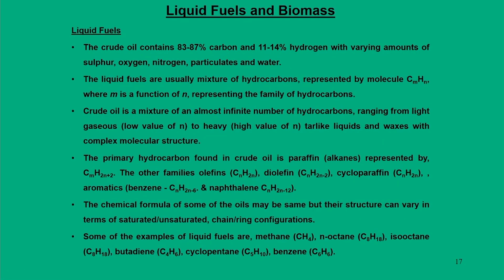So, now coming back to more details on the liquid fuels, if you see the crude oil, they contain 83 to 87% carbon, 11 to 14% hydrogen with varying amounts of sulfur, oxygen, nitrogen and other particulate matter. And normally these liquid fuels are represented in terms of hydrocarbons with a molecular formula of CmHn. Here m stands for the number of carbon and n stands for the number of hydrogen.